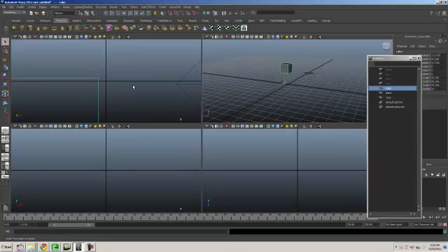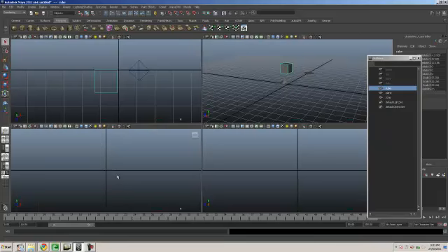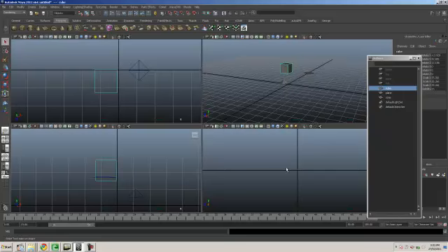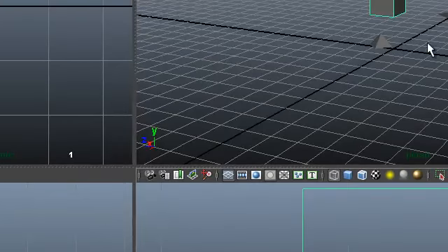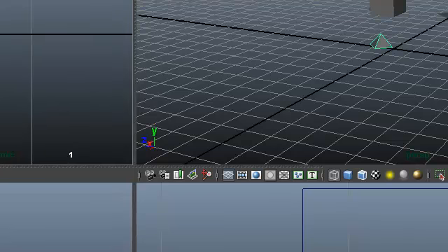So you'd select that and you hit F again. You're seeing this from the top view. Go in this viewport, you're selecting this. That's the front view. And notice that I just take my mouse to the side viewport, and I hit F. It basically just activates it. You don't have to click on the viewport to activate it, you just have to take your mouse there. So let's say I select it here, but I want to frame it in this viewport. I didn't click on the front viewport. I'm not clicking here, I'm just hitting F, and look what that did.